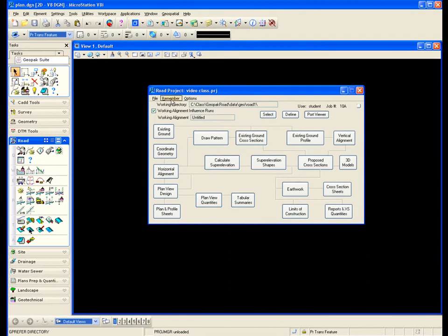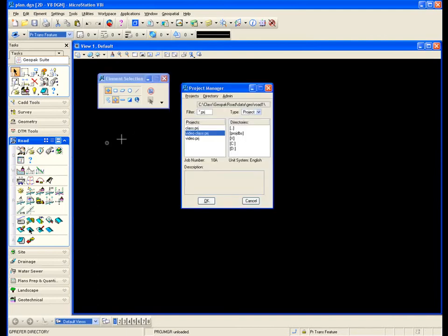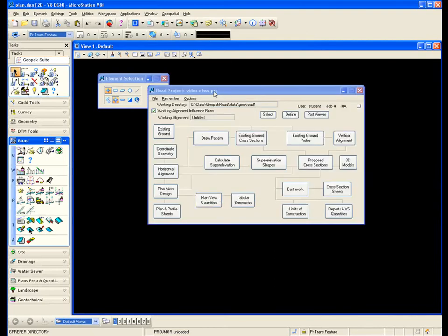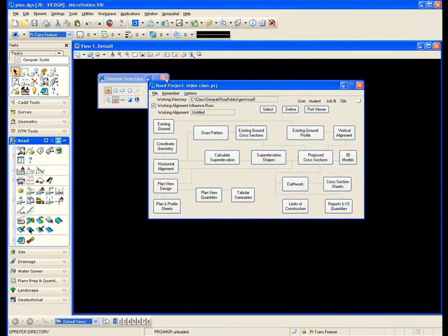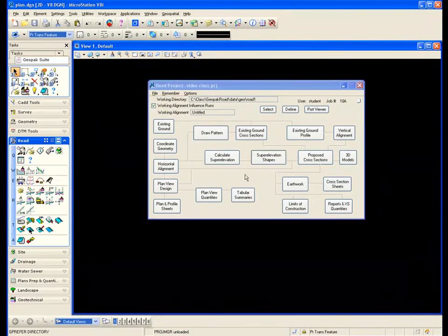So if you're working in multiple projects, just toggle Project off, and what that will do is whenever you close, say File, Exit, and go back to Project Manager, it will bring you to the project dialog box first, so you can choose the right project, say OK, and then it bypasses the user and brings you to here.